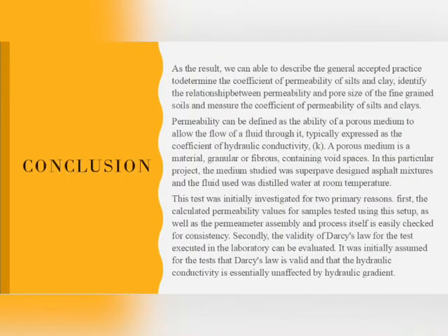I will explain about the conclusion of this project. As the result, we are able to describe the generally accepted practice to determine the coefficient of permeability of silts and clay, identify the relationship between permeability and pore size of the fine-grained soil, and measure the coefficient of permeability of silt and clay.